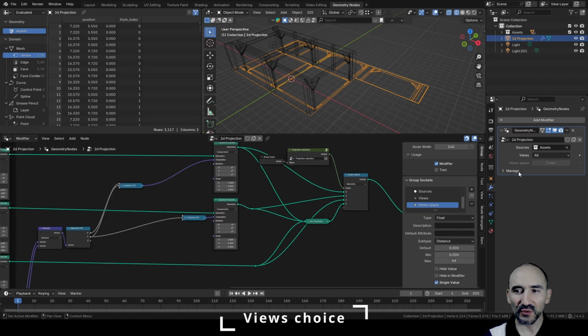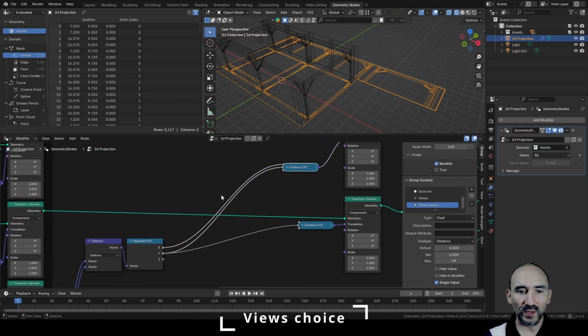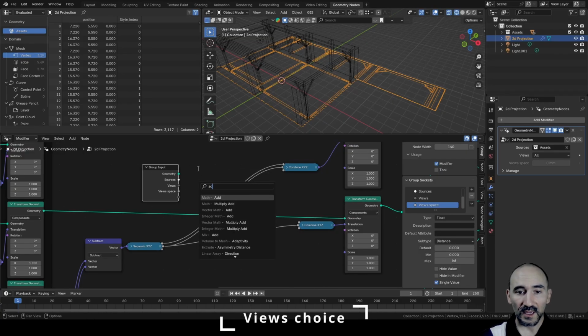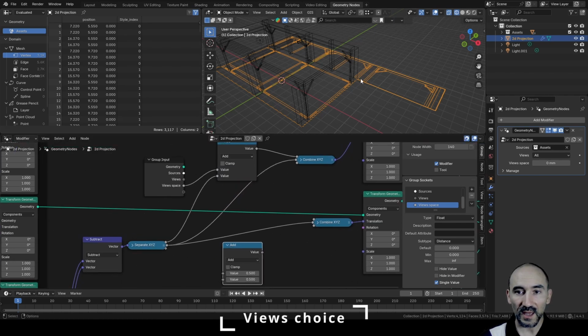And what we need is to use the same view space in addition to the offset we used before to place our 2D projections. So here, between these separate X, Y, and Z and the combine X, Y, Z, we need to add the group input and use this view space and add this result with the X and link this result in the X, and the same for the Y, because we want the same distance on the X and on the Y axis of these 2D projections.